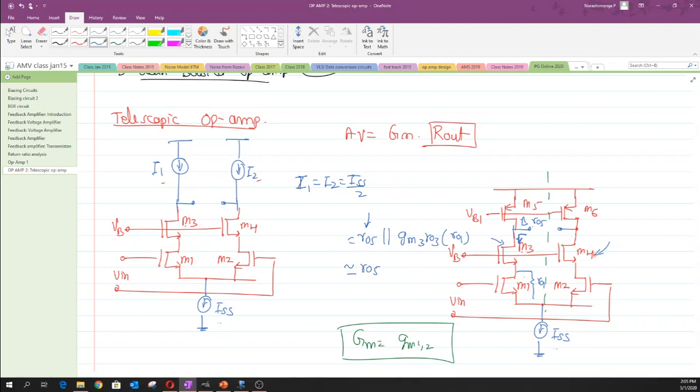So in order to really get the essence, or in order to improve this output impedance across the other end, that is across the PMOS structure, what one has to do is create what is known as a cascode structure even for this realization of this I1 and I2. So this is the actual structure that one has to use in order to create those I1 and I2 values, and one has to bias these M7 and M8 transistors with a particular voltage which we labeled as VB.